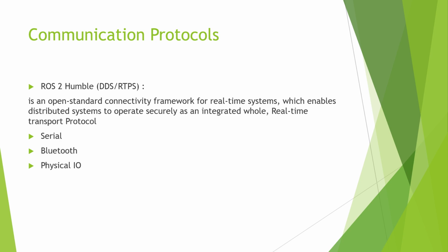So there's also physical I/O. Like in the case of the cutting blade, where I'm switching a solenoid, I'd kind of call that physical I/O, I guess. It's not really a communication protocol. It's just I'm putting voltage on a coil and it's switching. So those are sort of the communication protocols. There's a bunch, like the navigation stack is the ROS2 Nav2 stack. The camera is doing object detection. That's a custom object detector I wrote.